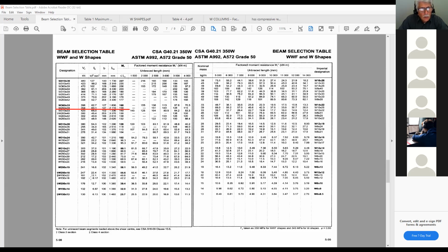Okay, so what was our MF value? It was 156. Okay, so you end up with a W250 by 39. And of course your shear should be more than adequate, because I think you had something like 90 for shear, and if you take 80% of 300, that would be ample. IX, you don't care because you're going to be doing it.